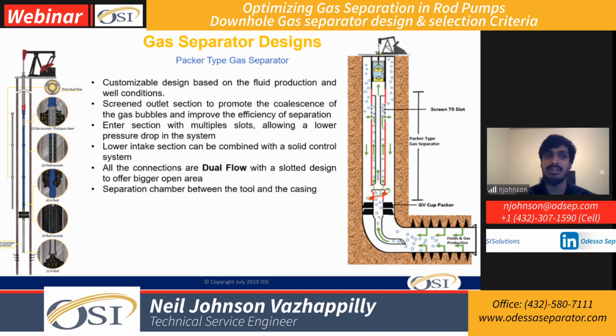As Carlos mentioned about the flow path, we'll go over that again here in a bit. So if you look on the left-hand side, the main three parts for this gas separator to work efficiently: obviously we're going to need a packer, right? Like Carlos mentioned, it could be a rotational packer, mechanical, cup type packer. They all have advantages and disadvantages, so depending on the well conditions, we need to see what works best.